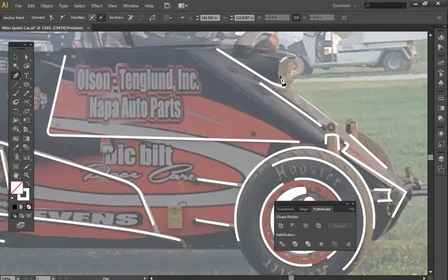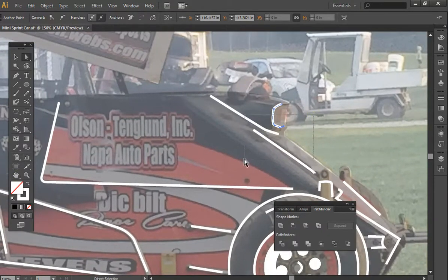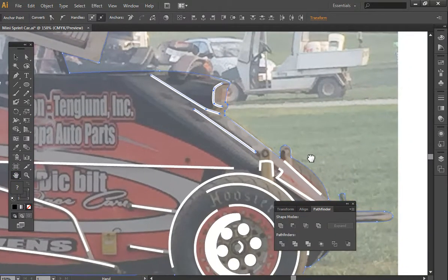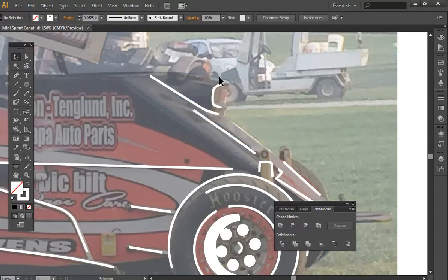Trial and error, and if you have any questions on how something's going to cut out, a lot of times what you can do is isolate these different items here, and you can export that as a DXF, and once you get it into your CAM system, you can actually just cut this little piece out on a piece of scrap and see if it's going to cut out correctly. If it doesn't, at least you're not out a lot of material. But it really will help you understand the clearances and your cutting system and what you're capable of, the level of artwork and detail that you're able to achieve with your own cutting system.